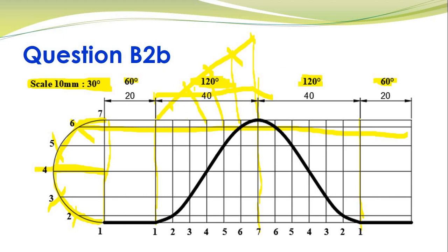I don't want to show that. All of this is shown in your lecture itself. So I will divide this into 6 equal parts, and then this is your return stroke. Again, I will divide that into 6 equal parts, because I'm dividing my stroke semicircle over here into 6 equal parts. And then finally label them 1 2 3 4 5 6 7, and then this is in the opposite order. So what I do is I can fix my points.